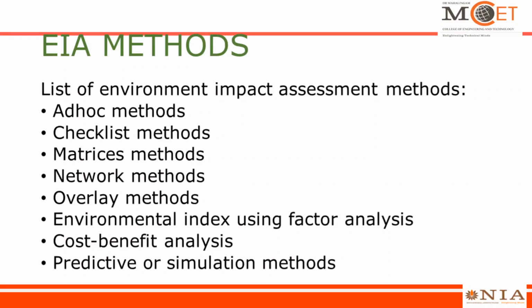So to avoid all this, I'll get a map with the location of all the wells, right? I'll get a map showing the elevation points. Elevation meaning how the surface topography is going down, going up. I'll get a map which gives the details about all the soil types in Pollachi, and then a map indicating the existing groundwater level in all the locations in Pollachi, and so on, right? So I may get all these 3 or 4 layers. Assuming that each of those maps is a layer, you overlay one layer on another layer.